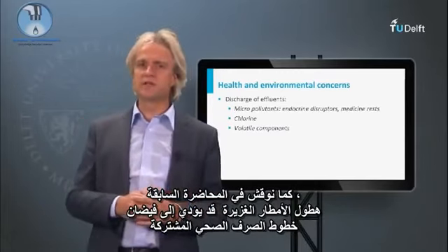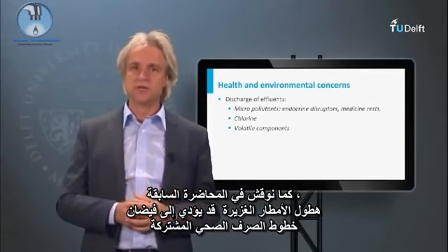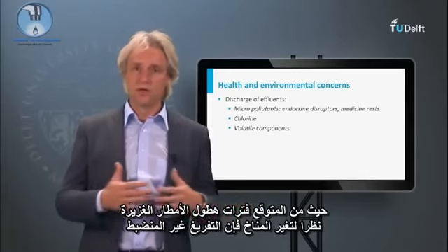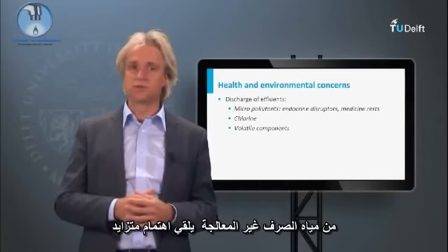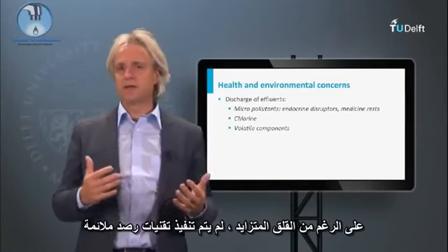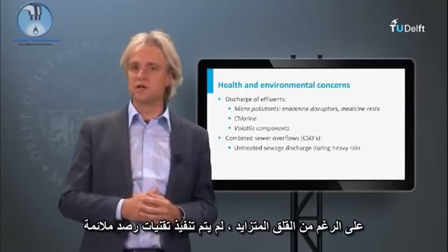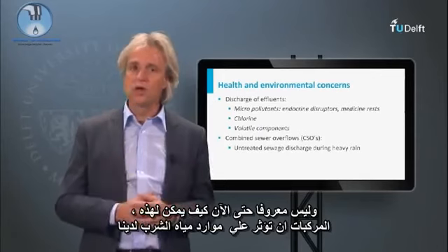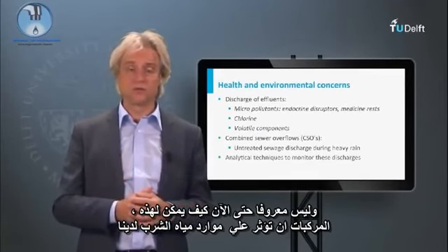As discussed in our previous lecture, heavy rainfall may result in combined sewer overflows or CSOs. Since more periods of heavy rainfall are expected owing to climate change, uncontrolled discharge of dilute, non-treated sewage is a growing concern. Despite the growing concern, appropriate monitoring techniques for the mentioned discharges are not yet implemented, and so far it is not known how these compounds will impact our drinking water resources in the future.